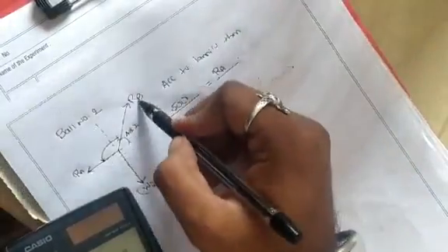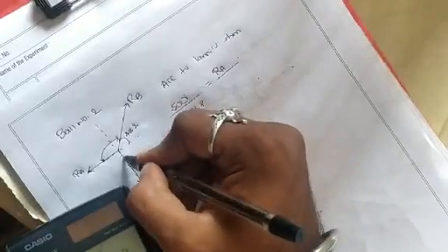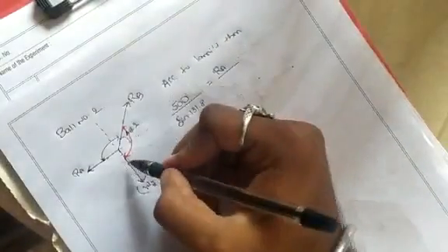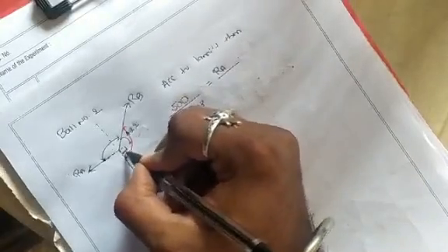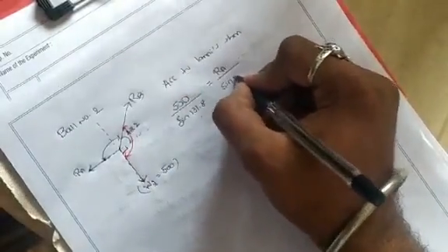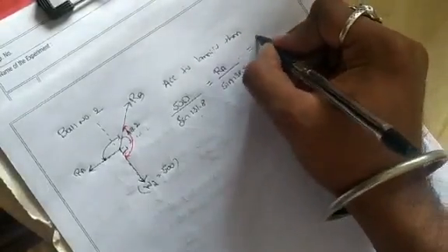Now the other two forces are RB and W2. That means I want this angle. One second, let me show here. Now I want this angle, right? From the negative y axis to the positive x axis, the angle is 90. That is from here to here, this is 90. 90 plus 48.2 is 138.2. So sine 138.2 is equal to RB divided by the angle between the other two forces, that is RA and W2.